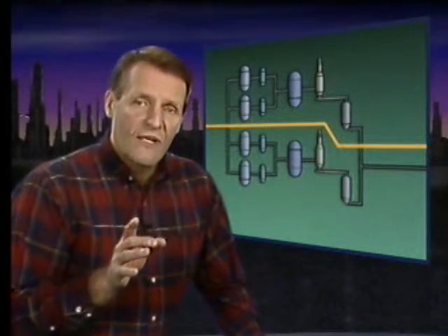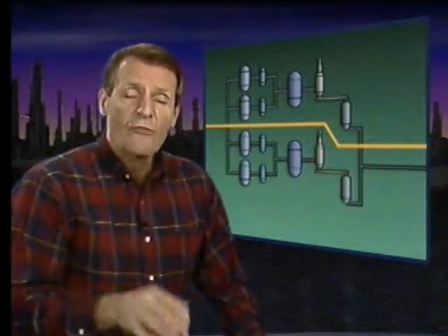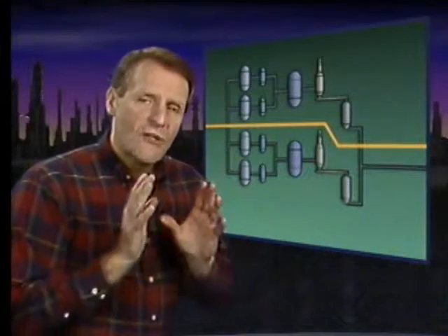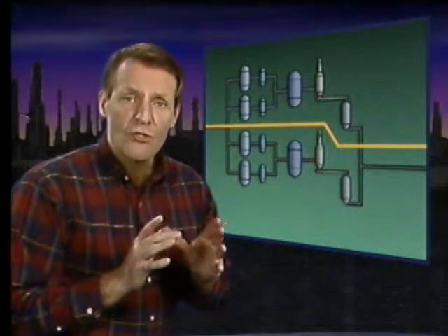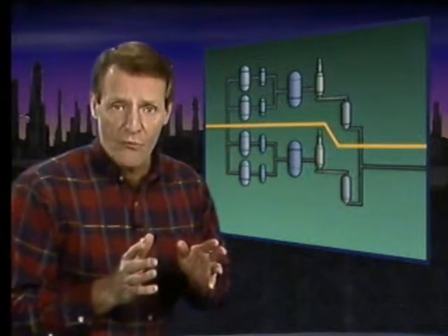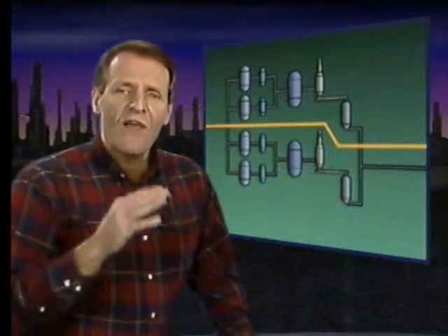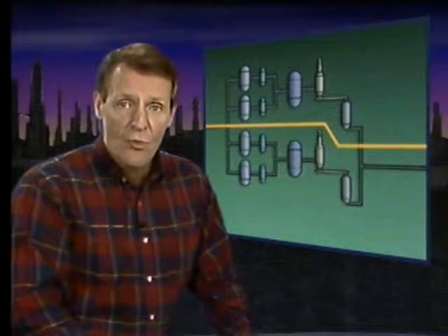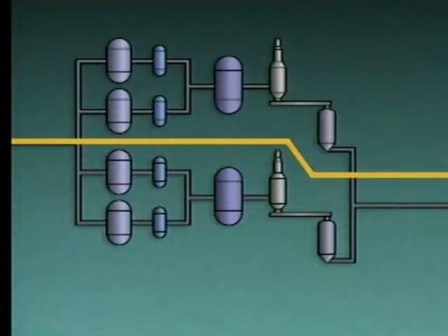A similar method can be applied on a larger scale through an approach we'll call bracketing. The goal of bracketing is to narrow down the location of a problem to a certain process or part of a process. Once you establish the boundaries of the problem, anything upstream or downstream of these boundaries is eliminated as a possible cause. As an example, this illustration represents a process that has two separate trains.